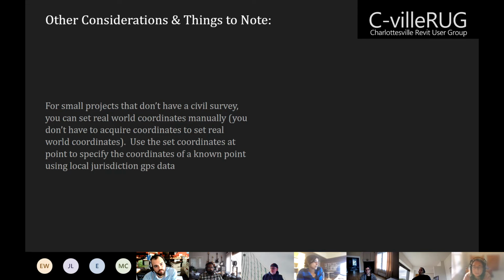And there's 2 methods you could use to do that. You could either click on the survey point and type in the coordinates, which, whether it's clipped or unclipped, will behave differently in those 2 scenarios. Actually, it might not let you change it if it's clipped. I think that's what will happen.